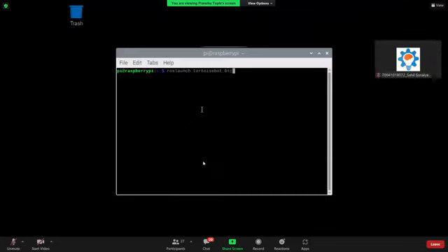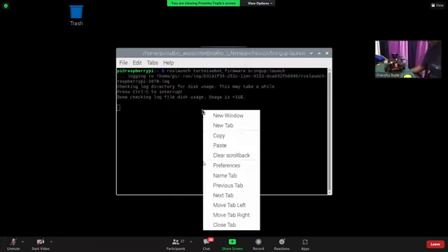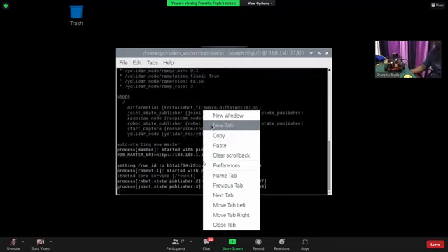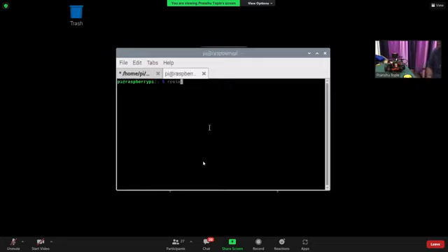Yes. So tortoisebot_firmware and bringup.launch. This will start the camera. And next our camera node that will do the ball tracking. So new tab, roslaunch. What was it? ball_follower and camera2.py.